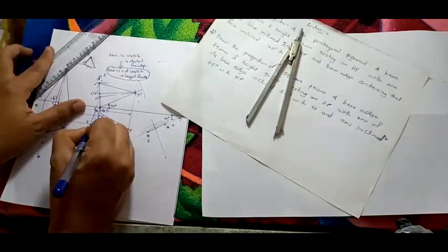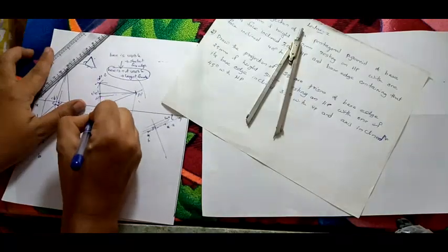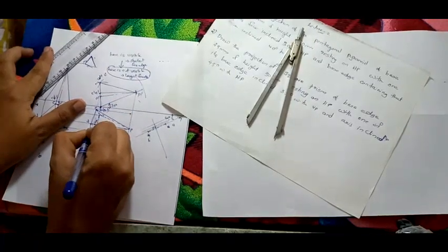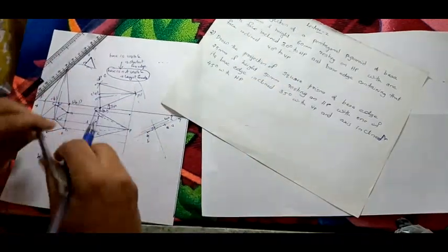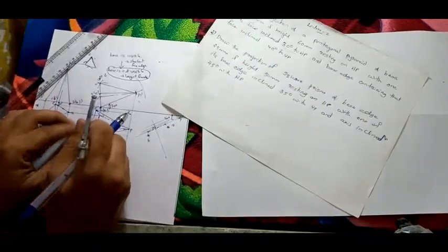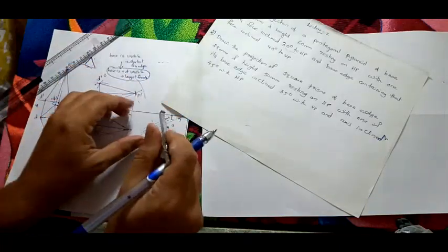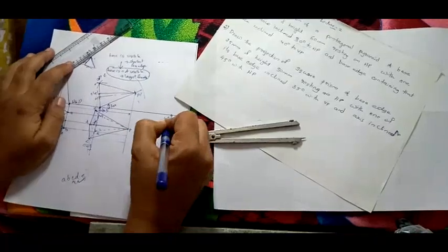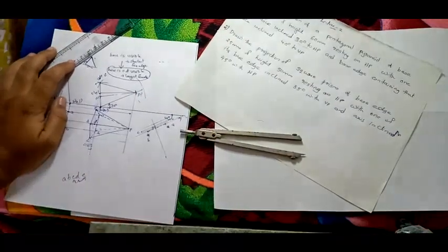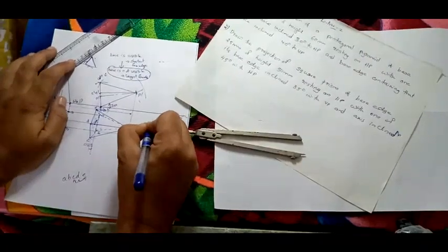Now on this will be O. So your O will be here, right? On this line, second line, first line O, second line you will be having E and C. How you will measure E and C? From here, this is the center line you have drawn, right? So these two distances will be same. So on the second line, cut it here on both the sides. This will be E, this will be C, right? And the last one is D, that is on center, that is here itself, you need not cut it.